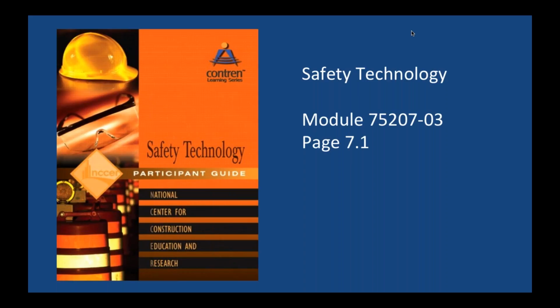They have to have emergency escape procedures, emergency escape routes and assignments. So basically, let's talk about floor maps or designs, knowing where our muster stations are going to be and how to safely evacuate out of the area. Then procedures that are going to be followed by employees who remain to perform any type of emergency shutdown work, or you may hear it called an oil and gas ESD, emergency shutdown, or critical operations before they evacuate. Not all employees can immediately evacuate. Some of them will have responsibilities to start shutting down units or equipment in order to minimize or reduce the risk of any more negative impact.